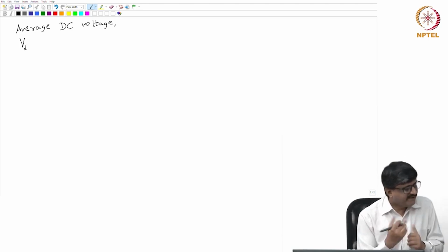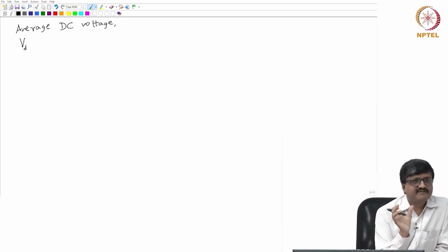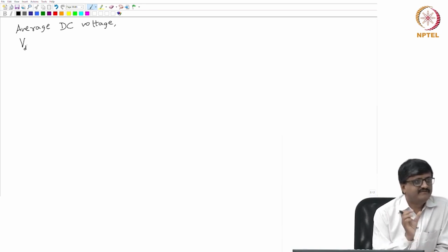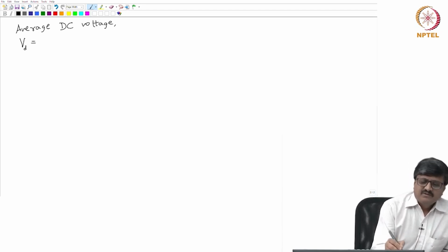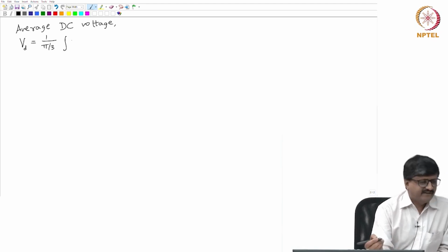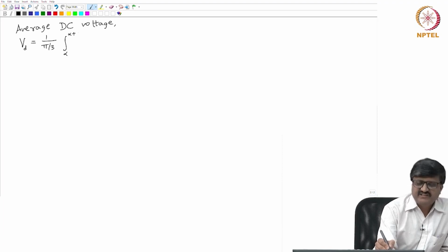Okay. So, what I can do is, I will take any one interval, which is of duration 60 degrees, that is 2 pi by 6. So, I will just integrate over one interval of duration 60 degrees and get the average value. So, 2 pi by 6 or pi by 3, so 1 by pi by 3. I can take any of the 6 intervals. So, the first interval is from alpha to alpha plus 60 degrees.